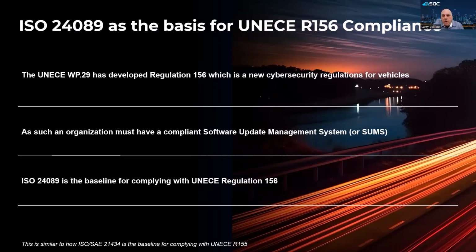Software updates, as per UNECE R156, have strong overlaps with cybersecurity. Unknown vulnerabilities introduced in software are usually discovered by hackers when something special happens, and this is then exploited as a route to launch an attack. Since almost all vehicle ECUs allow software to be reloaded, updates are a good way to fix software vulnerabilities. So OEMs must prove that they have a SUMS in place, they must demonstrate its effectiveness and use, and they must continually review and maintain them. This must be verified by a technical services agency and certified by an authority such as KBA in Germany.